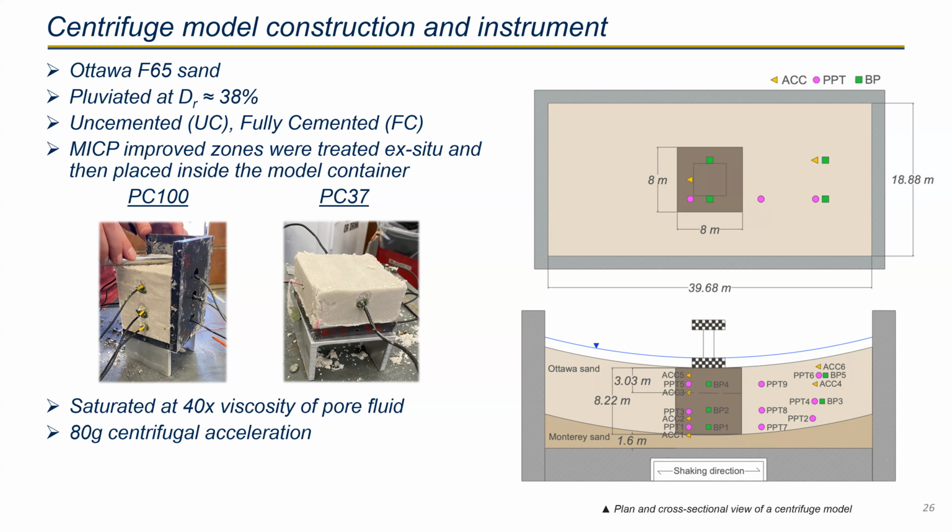Thank you very much. Also, I wanted to know, what is the time for this chemical to get hard? Are the depth, time, and humidity of the soil also affecting it or not? Oh, so basically we are using bacteria, so it's affected by lots of various factors like temperature, pH, and everything. But in an ideal lab condition, it also depends on the concentration of the chemical solution that you use. For our recipe, it only takes 8 to 12 hours to use about 80% of the chemical that we injected.